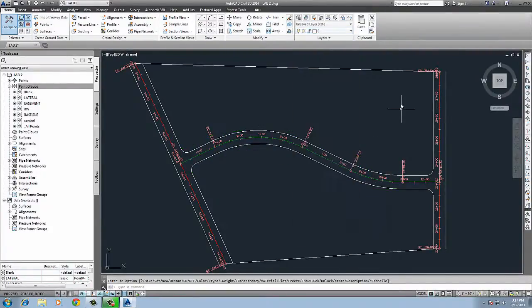So there, it's gone. And if you haven't ever used the little routine I'm going to show you, it's a great little routine in AutoCAD. It's called the boundary command, or bpoly, and what it will do is allow you to select an internal point to your area, generates a polyline for you around this, and you can then use that polyline to list out information. I use this very often when I'm building subdivisions and checking lot closures and those kind of things.